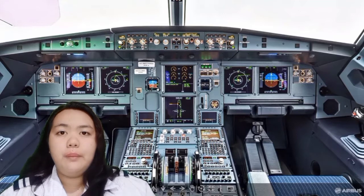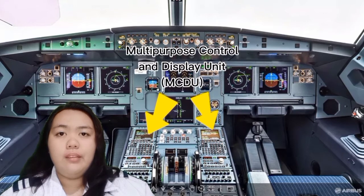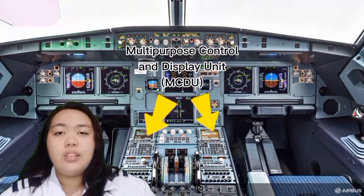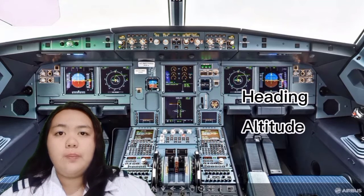The automatic mode is used for most of the flight time and is programmed through the MCDU or the Multi-Purpose Control and Display Unit. The flight plan is inserted in the MCDU to be used as a reference for the autopilot system. The flight plan contains information such as the heading, the altitude, and the speed at which the aircraft should fly.